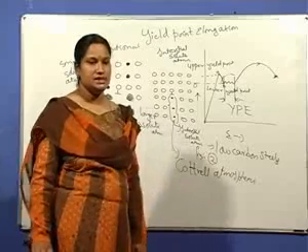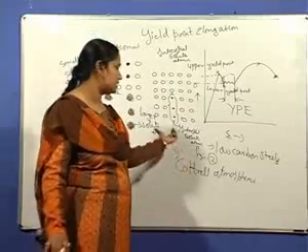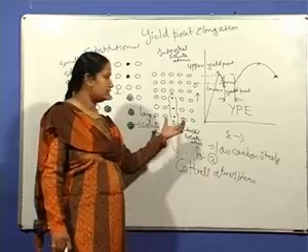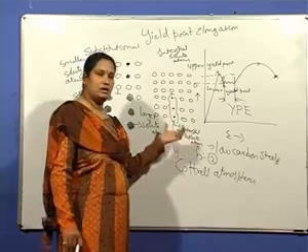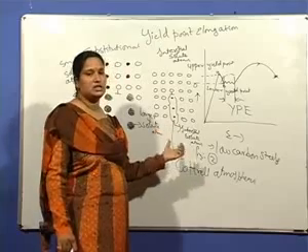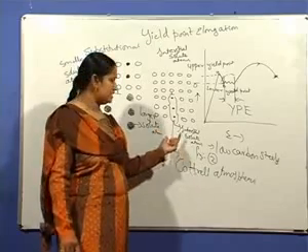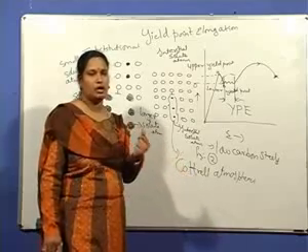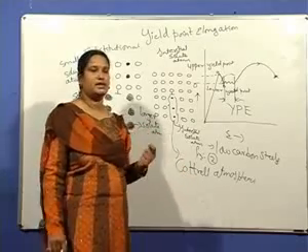So the dislocations are locked by these Cottrell atmospheres. These atmospheres are the barriers for the dislocation motion. And these atmospheres cease to operate. That means they do not operate beyond 400 degrees centigrade.